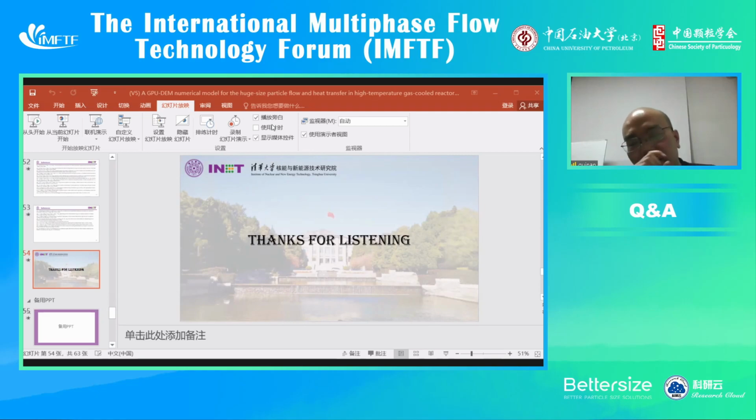Okay, in fact, we did not use Voronoi cells for industrial scale computation. Because when the particles move, the Voronoi cells need to be rebuilt, so it's time consuming. So we abandoned this approach and used another approach, using a neural network to calculate the view factors between the particles. And we did not use Voronoi cells for dynamic simulation of the pebble flows inside the pebble bed.